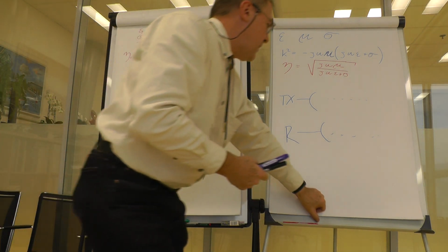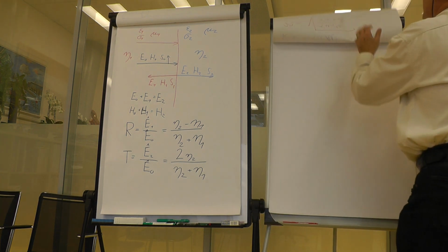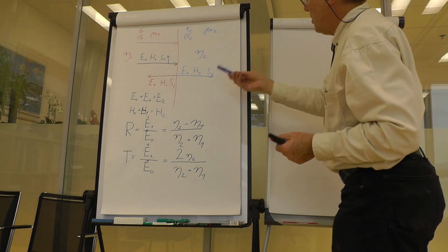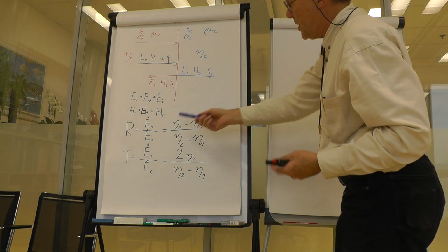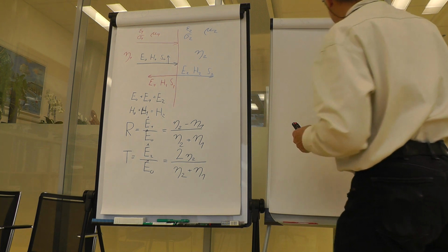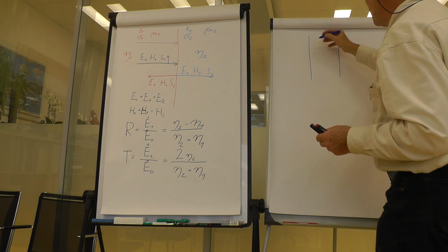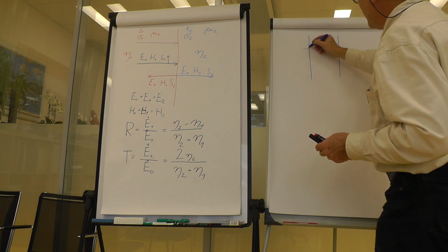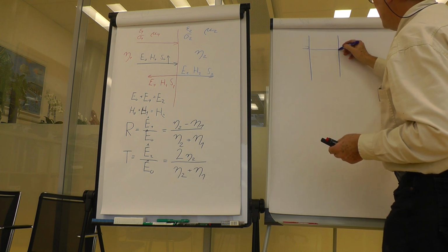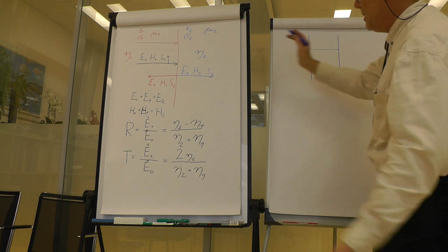So we have a metallic surface, and a metal by its nature has zero or very small impedance, so it causes a total reflection. So you have a metal, and then you have something on that, and that something should first not reflect here, and it should damp the signal, so after it comes to the metal it's already damped, so there will be no reflection.